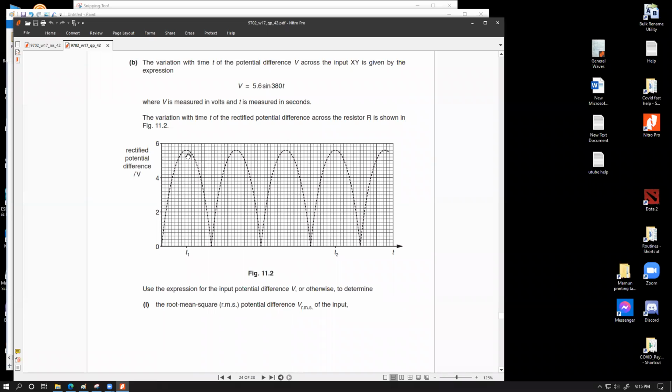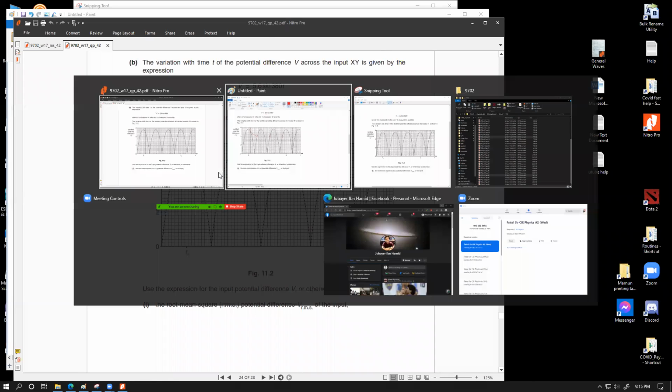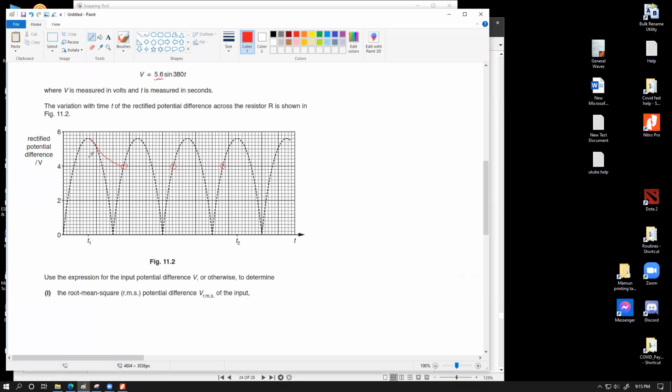Without the capacitor, the ripple is altogether 5.6 because it is going all the way down and all the way up. Whenever you use the capacitor, the ripple reduces to 1.6, which means the ripple would be limited to 1.6. So we will still have the ripple happening for a value of 1.6 over here. So up to this 4, we have a stable value. The ripple is limited to 1.6, not the whole output voltage. Okay. Okay, sir. Beautiful.